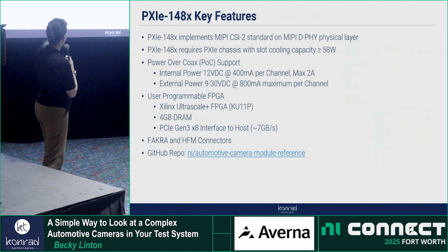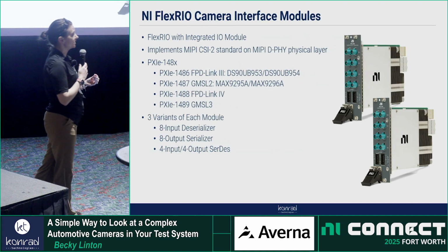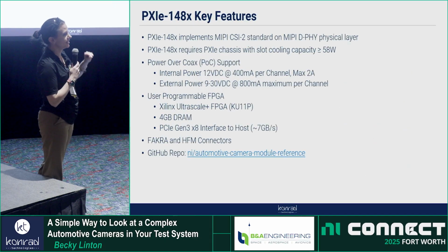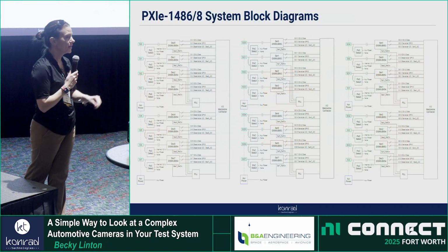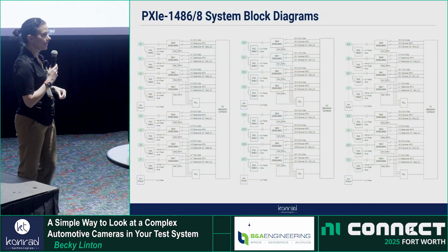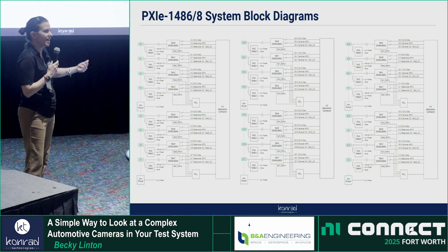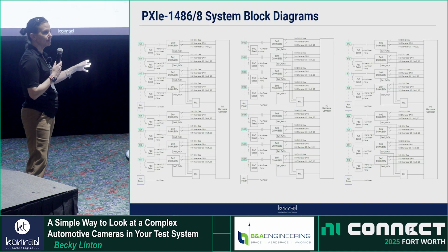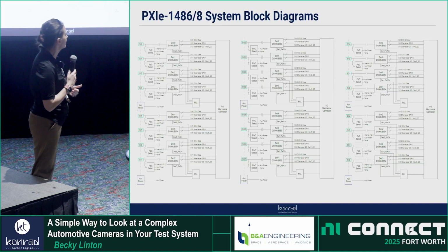So go back. The 4-in, 4-out has a dedicated serializer and deserializer per channel. The deserializer card that is 8 channels has 4 dual channel deserializers. So we had to do a lot of special stuff because when we're programming, those 2 cameras have to be the same, which for us, it's kind of okay. We made the restriction to the customer that one bank of 8 cameras has to be the same type, so they can only program those all in the same script. That was a restriction we put in.